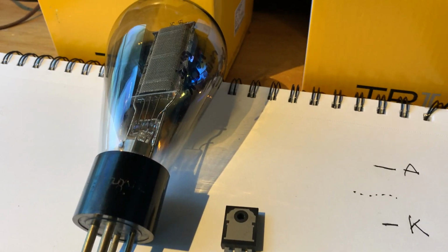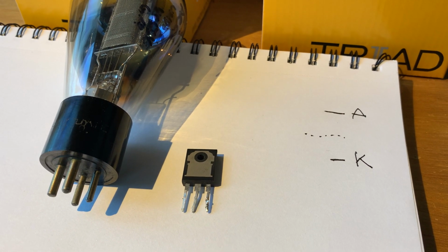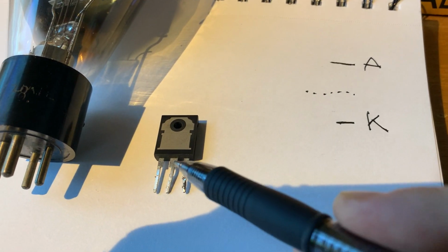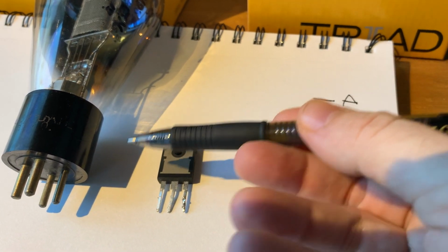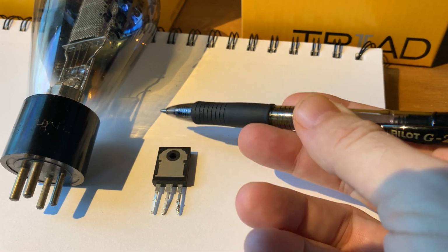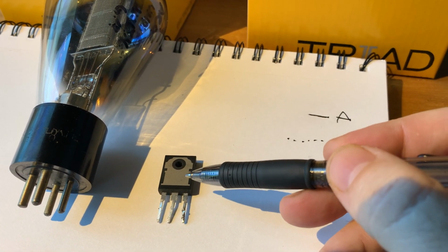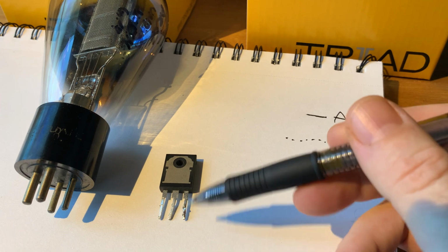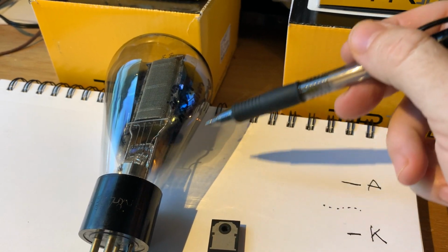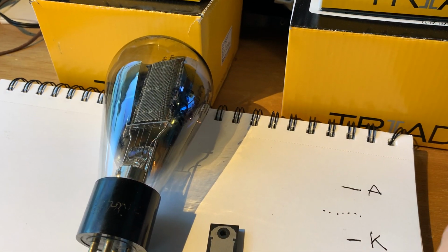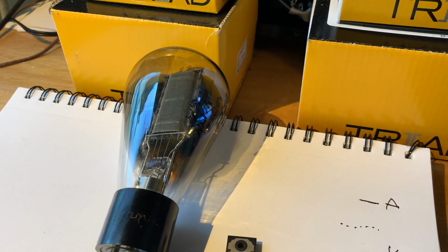So transistors do not have filaments. We cannot see the inside of a transistor because it's covered up in a chassis. All we can see is that there are three legs, plus this metallic part that we can mount to a heatsink. So we attach a heatsink so that the heat is dissipated, transferred away from the body, so you can use it for higher power compared to without a heatsink. For a vacuum tube, it's the large glass surface of the bulb that's conducting the heat away from the tube, and there are heat sinks for vacuum tubes as well.